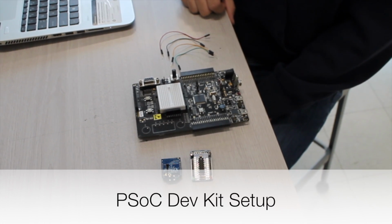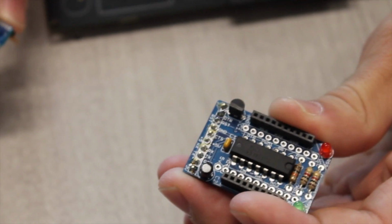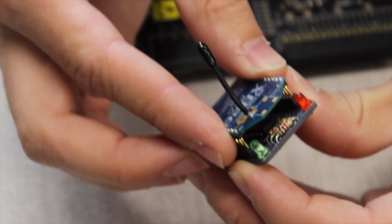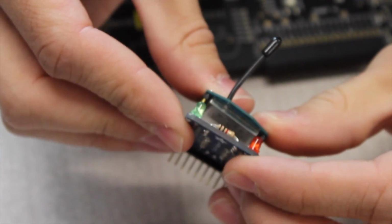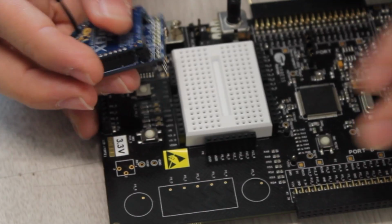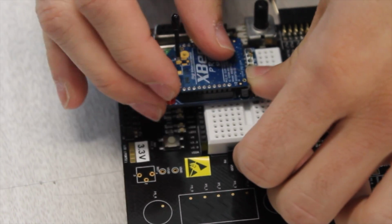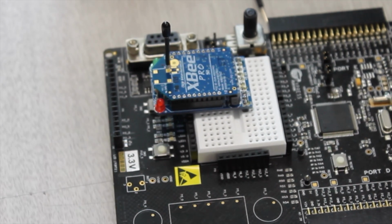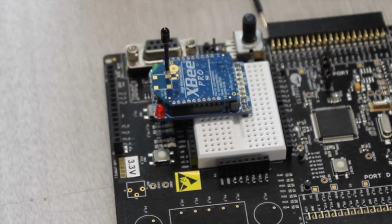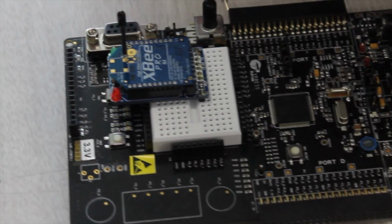In this segment, we will be attaching the XBee module to the PSoC. Take the second adapter board for the XBee and insert the PSoC XBee into it. Now, using the breadboard on the PSoC dev kit, insert the XBee. To interface the XBee with the PSoC, there are 4 pins that we'll need to access. The first one is 3.3 volts.